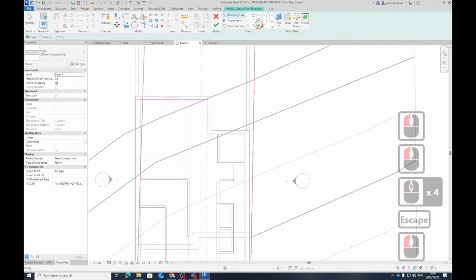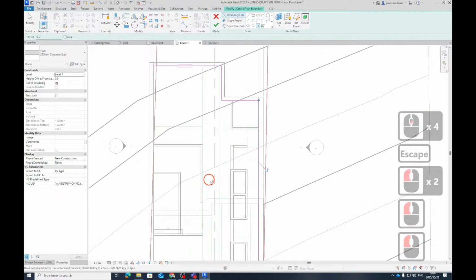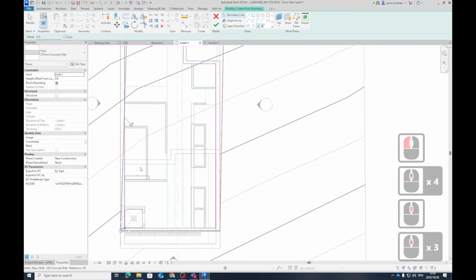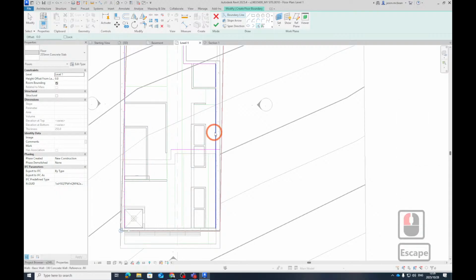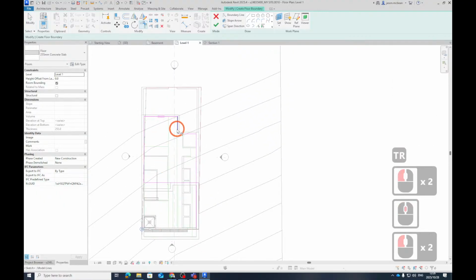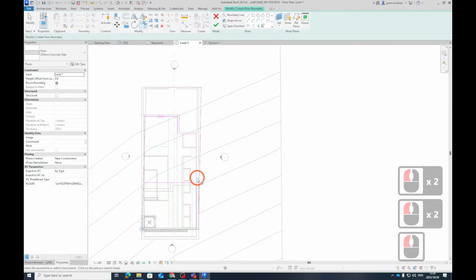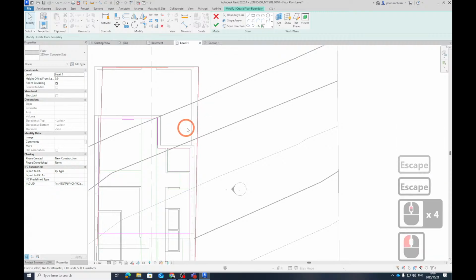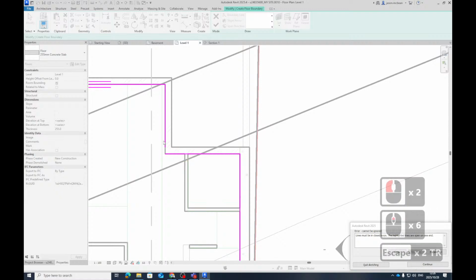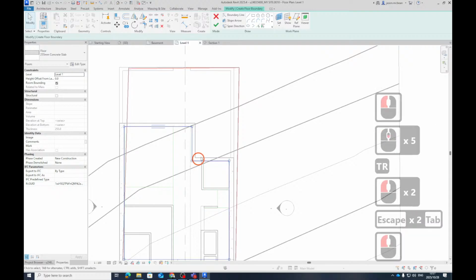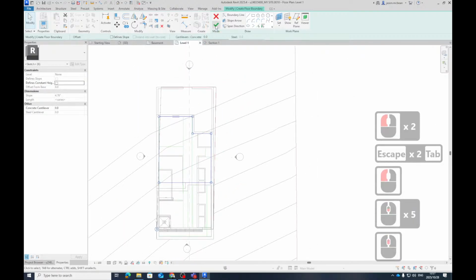I'm going to go here again. So maybe there, I'm going to go there as well. So that's set on my floor slab. Then the floor slab might stop here for now, because there might be a void here, just for argument's sake, you can tweak this. This is the problem. Sometimes when you draft something, it's just easier, because in Revit you spend so much time, it's complicated. So I've put a floor slab in there, and it's a 255 slab. There's a little opening there, forget that. So trim. You must just make sure that this is a closed set of loops, which it is now. Press tab, good. Finish that.